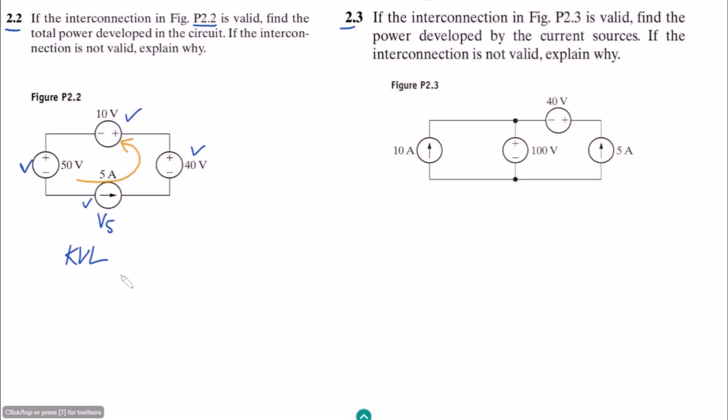So this is what, let me call it V40. Okay, V40, and here we can see that current is entering through negative and coming out of this source through this positive terminal. So I am taking it positive. Here we can see that current is entering through this positive terminal and coming out of this negative terminal, so therefore I am taking it negative. So minus V10 here again.